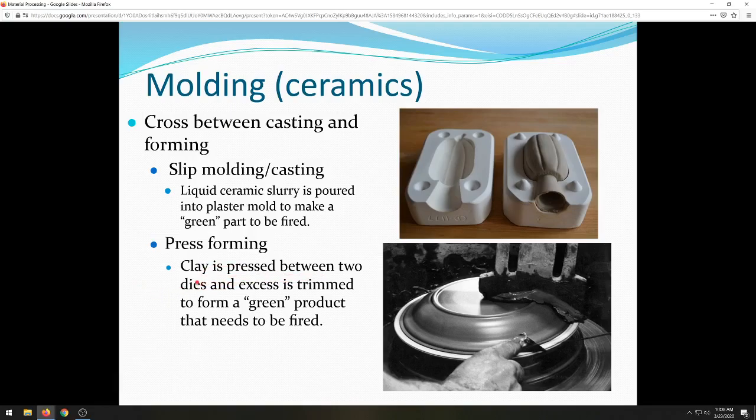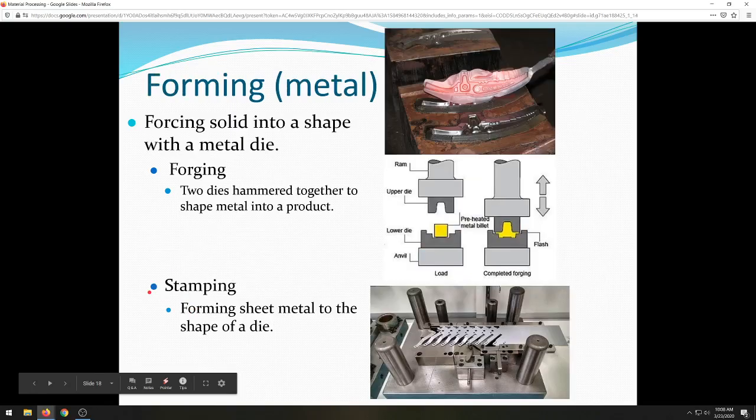Sometimes it's just a stamping process, and there's no actual spinning involved. You just squeeze clay between two mold halves, and then you trim the excess, and then ta-da, you have a final product. Removing the products from these tools can be tricky, though. Sometimes you just let them sit on this platter here. Sometimes air is injected underneath if you have ports for that. Sometimes you just very, very carefully remove them. But to not deform the clay is really tricky.